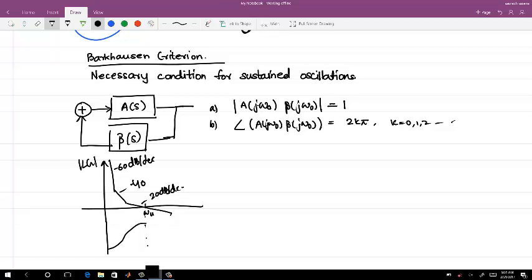I'm just saying that you can have a phase somewhere around minus 180 degrees, minus 270, and a gain greater than 1. But this system is a stable system. And this system will not oscillate either, if you have a certain phase margin.